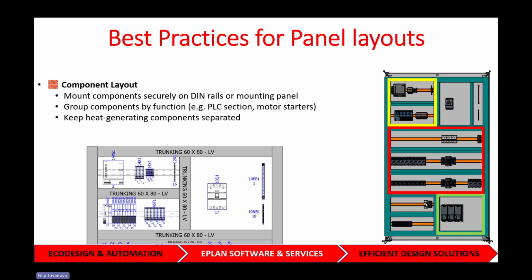And while you're keeping the VSDs separated, you also need to think of mounting clearances for anything like VSDs or even power supplies. So typically with VSDs, we would go for about 50 to 100 mm above and below the VSD. And maybe sometimes there might be side clearances. Of course, these are just typical values. You would have to check the data sheets to make sure you get the correct one.